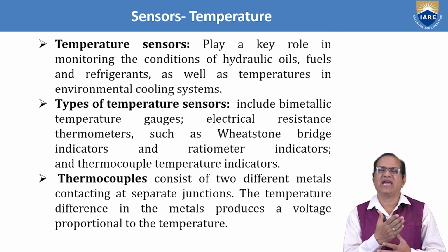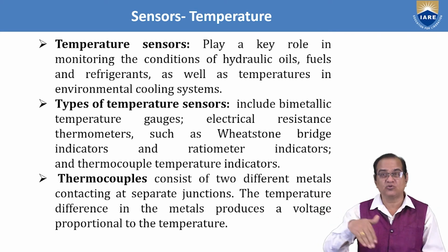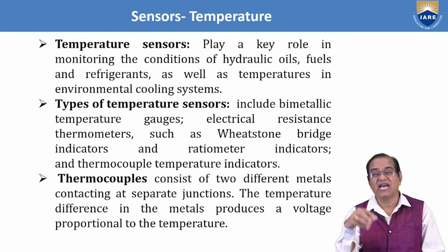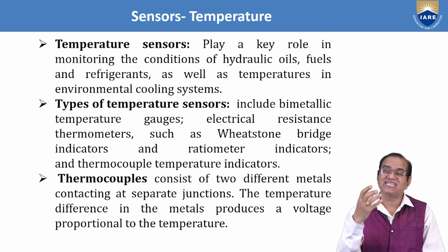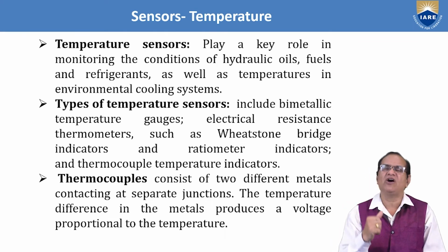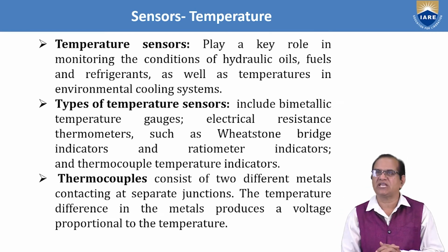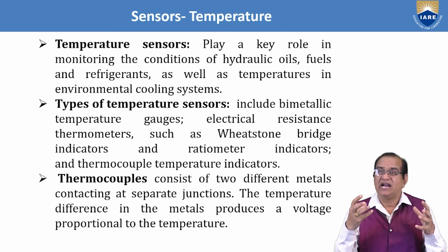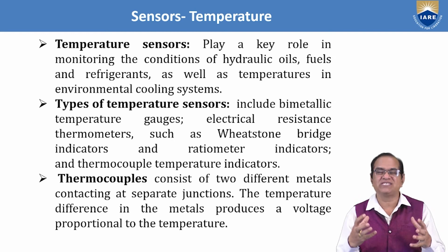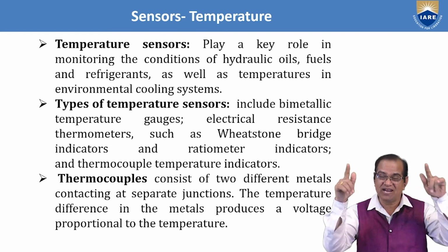This has to return back, and after returning it has to go again to the tank, so it has to be cooled. So the temperature sensors are there: up to what level we have to cool, and what is the maximum temperature at which the oil is working. All these things have to be monitored.